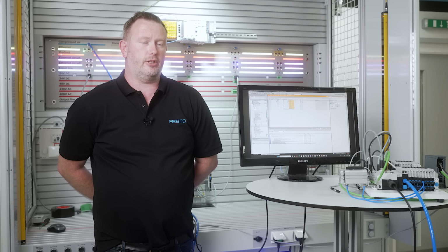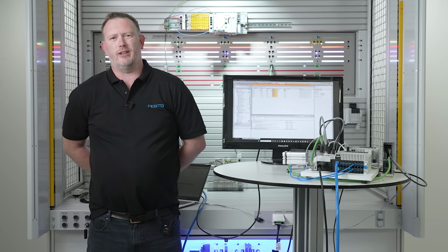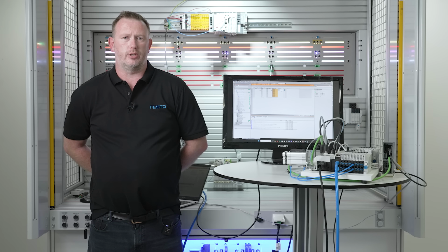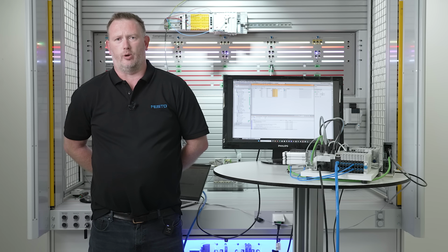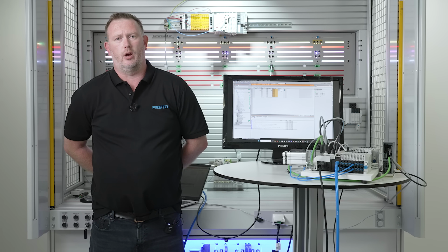So now we have our connections there. It's important to talk about diagnosis. From a diagnosis perspective, both the commissioning software, in this example Festo Automation Suite, and the PLC can fully diagnose the system. Generally the system, if it's green and it's running healthy, then it'll be absolutely fine. But it may be a case that a wire has come loose, or one of the devices is not functioning correctly, or the power may have been lost. But these faults can be easily identified with the commissioning software, in this example Festo Automation Suite, or via the PLC controller itself.